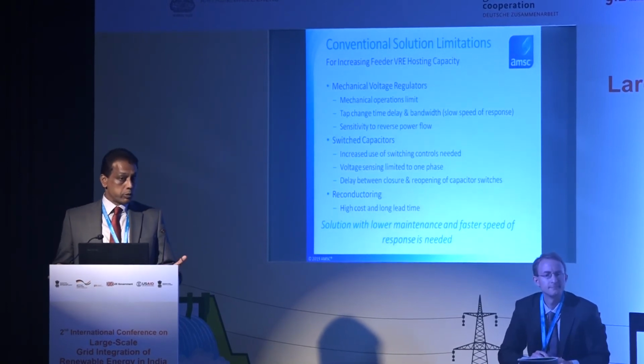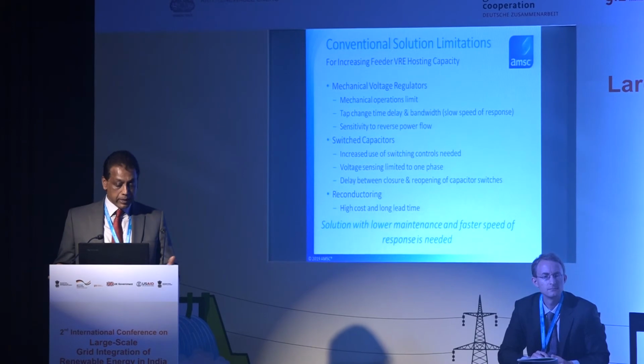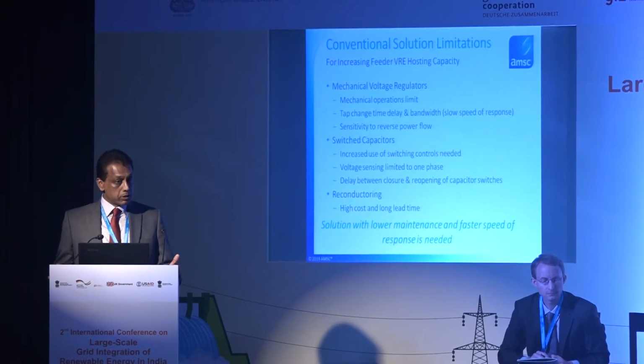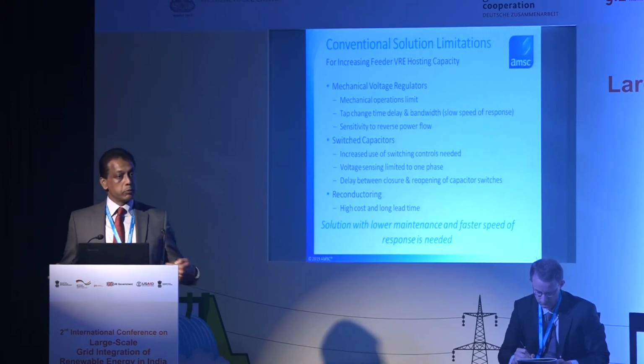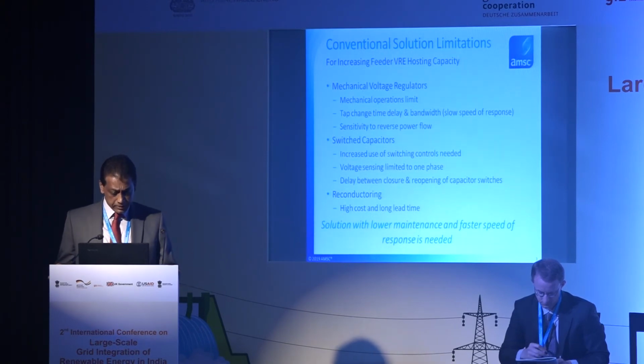You use switched capacitor banks. You can switch them in through automatic switching controls, or you can just do it on a time of day basis. But you switch them in and out based on some study or understanding of what impact it will have when you switch it in, and what impact it will have when you switch it out with regards to the step voltage change.